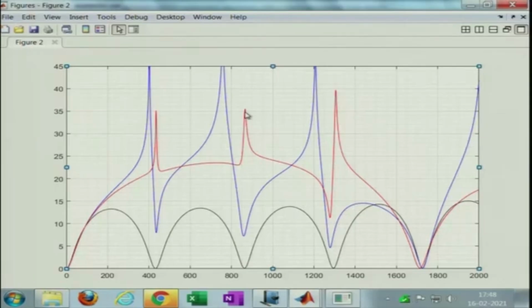But then we have to wait and watch. For experimental results, there will be full contribution by the 3-dimensional modes. There will be evanescent waves generated at the interface, where the perforated pipe starts and where the extension ends. So, at the interface there will be higher order modes generated. All the tuning that we are talking about is just based on the plane wave analysis.